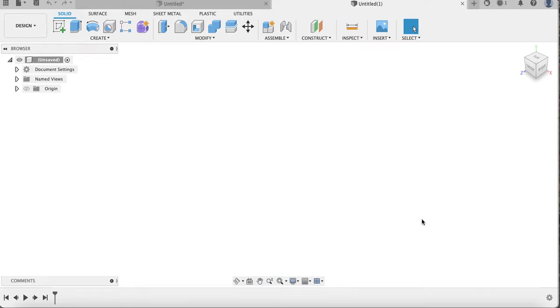And then I showed you how in Fusion you work in 2D space and then convert that over into 3D space, through using, I know we're familiar with the term push-pull, but we use the term extrusion, which is more of a technical, engineering term. So in Fusion, it's called extrusion. We're shedding away this idea of push-pull that we have in our minds from SketchUp. So I showed you how to create a 2D sketch and then extrude it into 3D space.